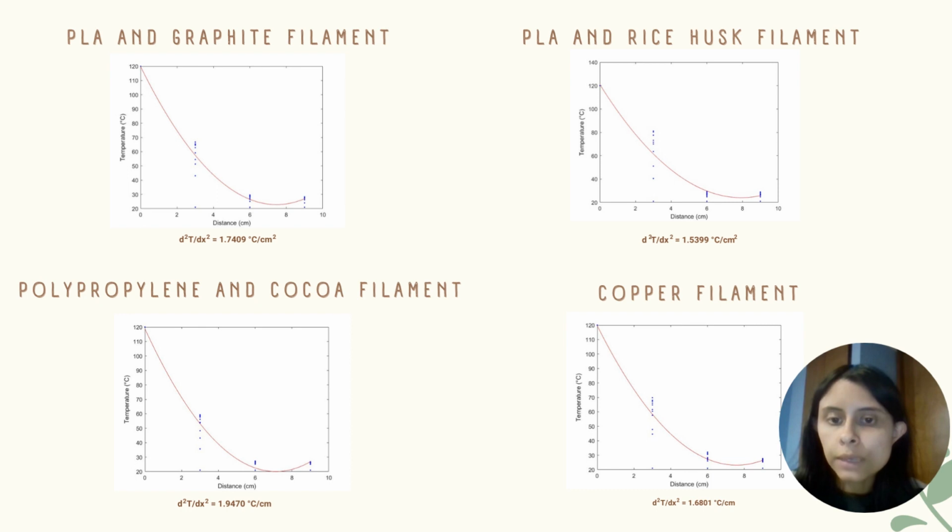All the jumps happen in the 3 centimeter mark. Relating this to the data, it is possible to see how in each measured length there is a different heat transfer. This confirms the anisotropic behavior of the materials. The fact that they are anisotropic explains that they have different properties in the direction that is being analyzed.